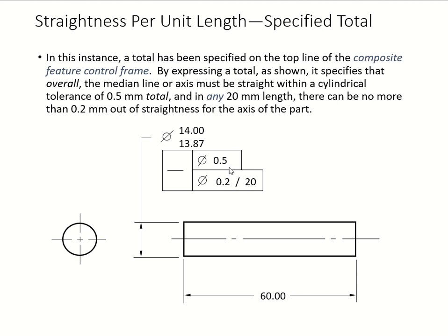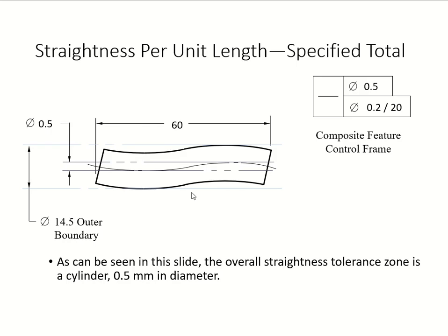So you can't go anything more than 0.2 millimeter outer straightness, yeah, for that excess of that part, because it gives you another tolerance that you need to pay attention to. So let's go and take a look at it. Yeah, so here is our variation.